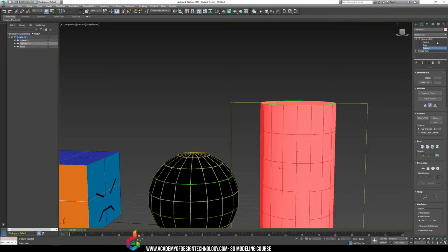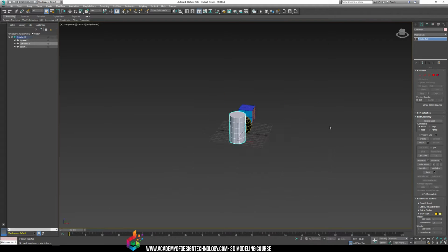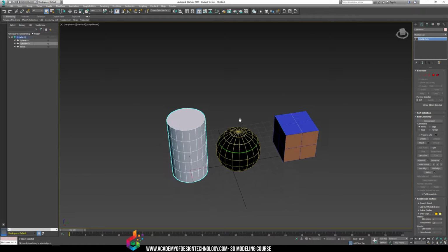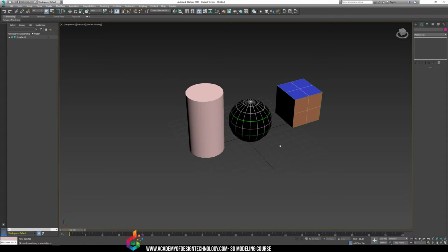And I want you to render the cylinder out, and make sure that you get that done as well. And get a texture map loaded for it as well. Don't forget to do the same process we did for the sphere in the box. Then collapse, save your UVs, then collapse your unwrap UVW into your edit poly, and everything should work out just fine, and you have these three objects.